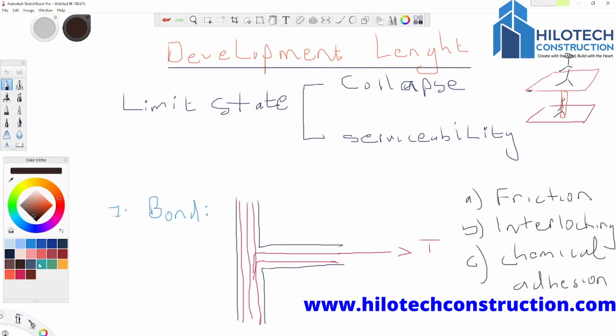First, friction. When you pull this rod out like this, you are going to see that since it's a mixture of the rod and the concrete, there's going to be a frictional force that is going to act this way. As you can see, the frictional force will act this way, thereby preventing this rod from going out. Okay, so no matter how much you pull it, you see that this rod cannot come out of this beam. Why? That is because of this frictional force which is being exerted by the concrete that is embedded with this rod.